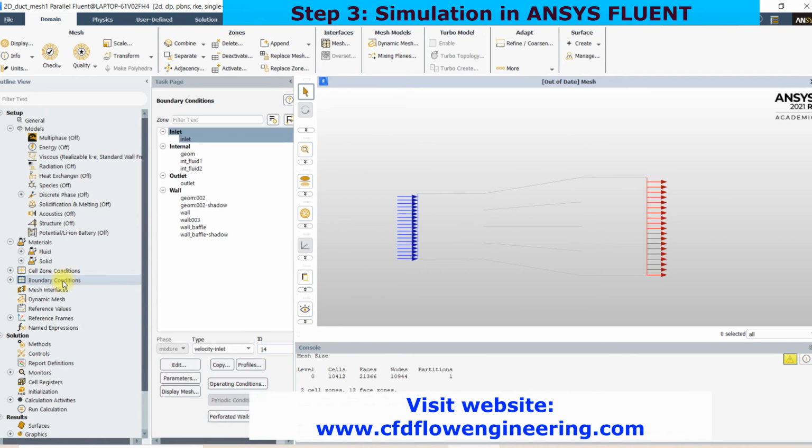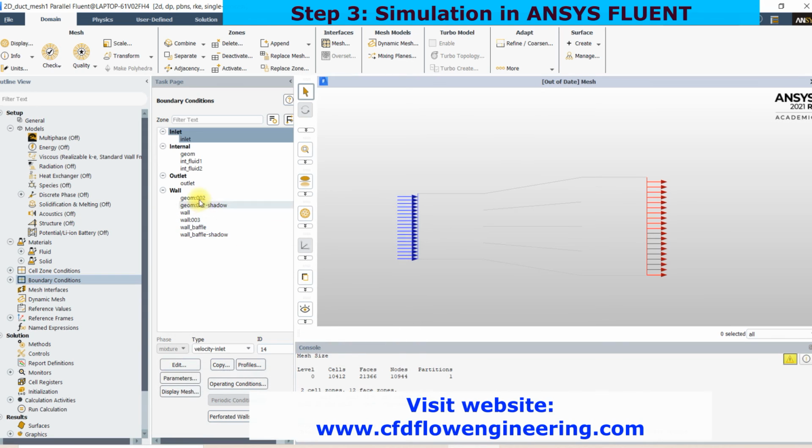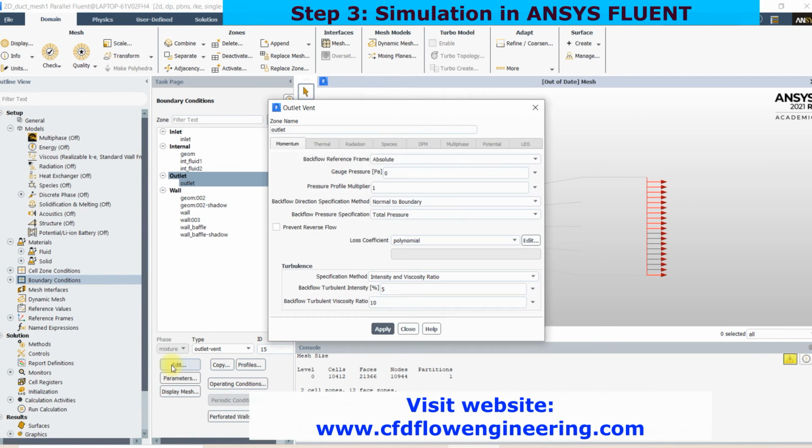Then go to boundary conditions. Inlet is defined as velocity inlet, 3 meter per second. Intensity you can give as an average value, and for the outlet you can select outlet vent. You can take -5 Pascal.